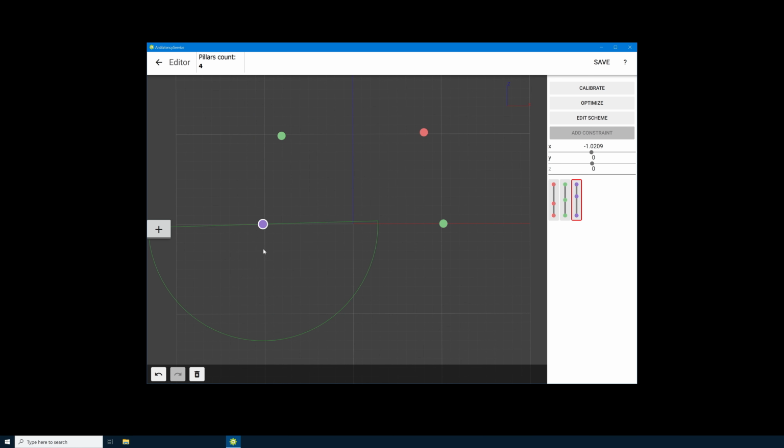To set the viewing direction of the reference bar, hold down the Control button, left-click on the selected reference bar, and then drag in the desired direction. For this tutorial, I will be leaving the direction and viewing angle of the IR markers at 360 degrees, which is the default. But if for any reason you need to change this, that's how you do it.